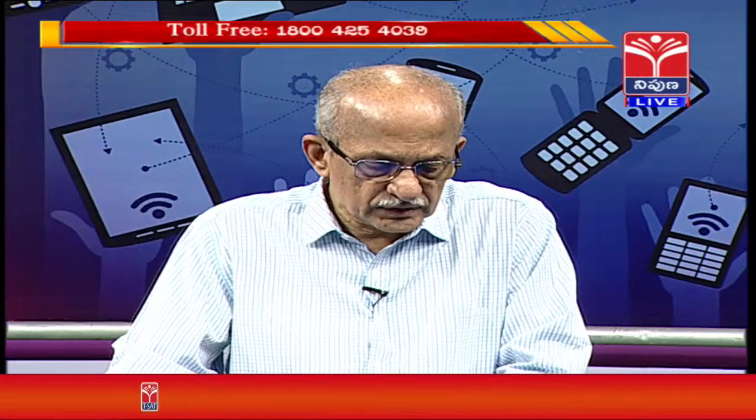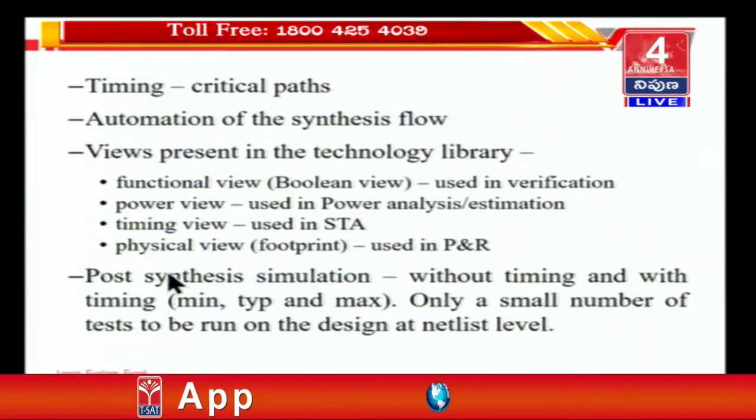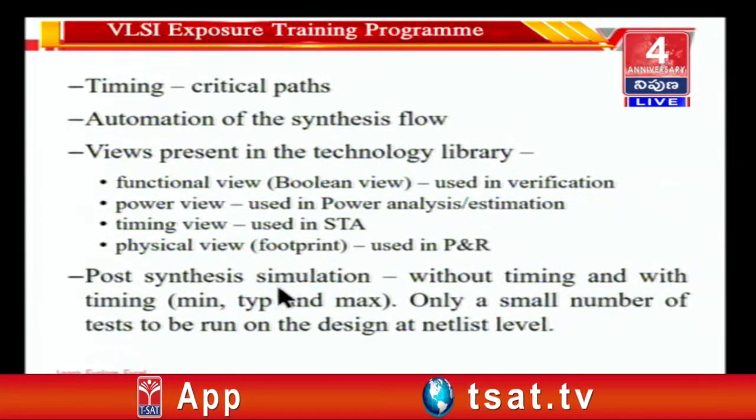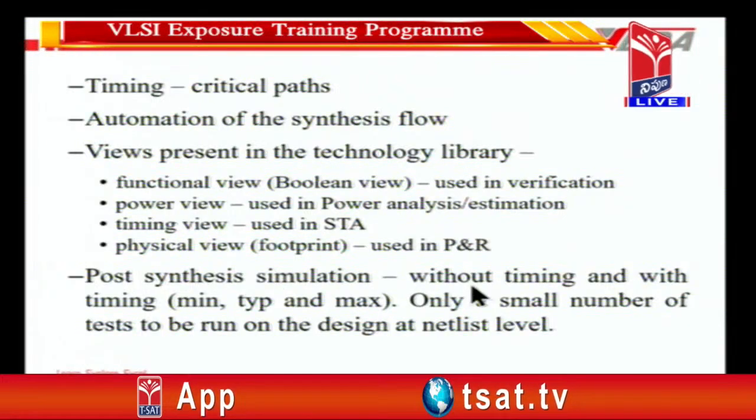These are the checkpoint tests. If you run these tests and they pass properly, then you can say with a very high degree of confidence that the synthesis process and the code that was written at the RTL level has been properly transformed.